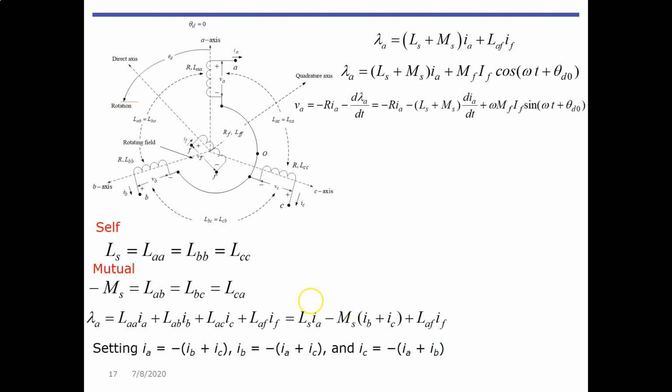The modeling part is a little bit simplified in this lecture compared to a full-blown model. But the idea is very good, and we can look at it. Of course, we have a self-inductance, something you have seen on the transformer. So we can represent one Ls for the L_AA, L_BB, L_CC self-inductances. And for the mutual, we often use the Ms here, representing the mutual inductances.